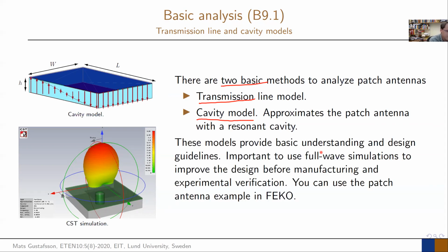So what the models do is that they provide this basic understanding, really the fundamental understanding of how your patch antenna works. And it will give you design guidelines. So when you start designing your patch antenna, you will get the idea of how big it should be from these models. And then afterwards, it's very important that you do full wave simulations to improve the design.